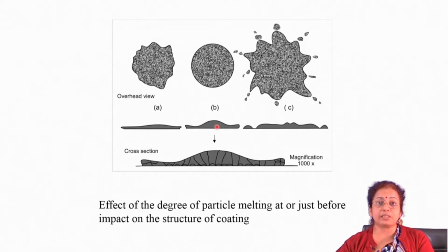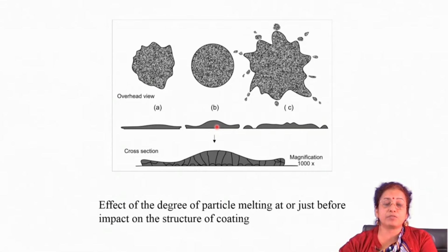But again, as I mentioned, there are a large variety of thermal spray deposition techniques, like in kinetic spraying, where you use totally cold particles sprayed over the surface of the substrate. In that case, you have to apply very high velocity so that the particles get impinged, and you get a very high density coating which is strongly adhered to the surface.